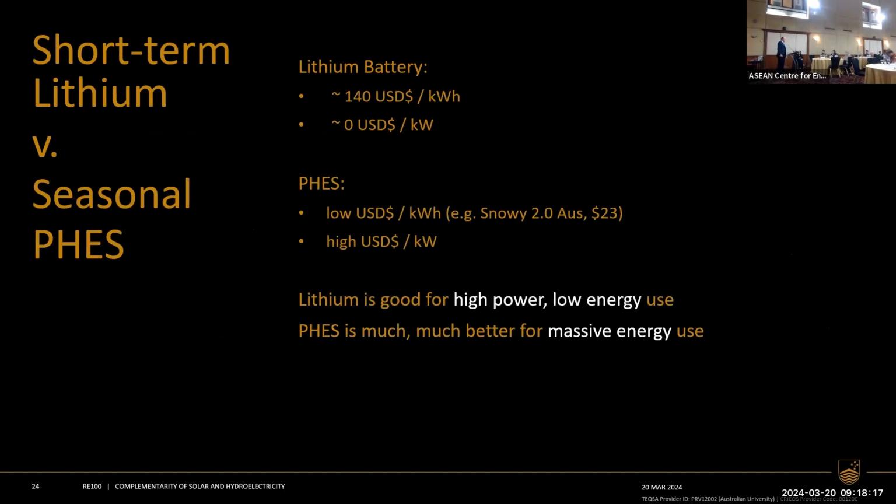So comparing lithium and pumped hydro, lithium batteries are generally quite cheap on the energy and the power front. Pumped hydro has relatively expensive power, but much cheaper energy. If you raise your dam wall by just a little bit, then you get huge amounts more water volume, huge amounts more energy capacity for a relatively small extra investment.